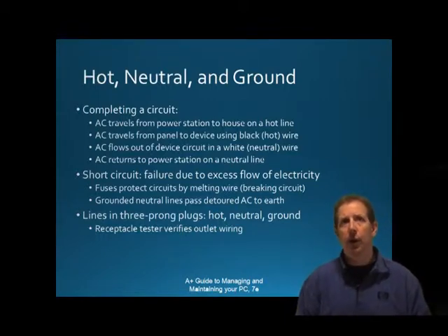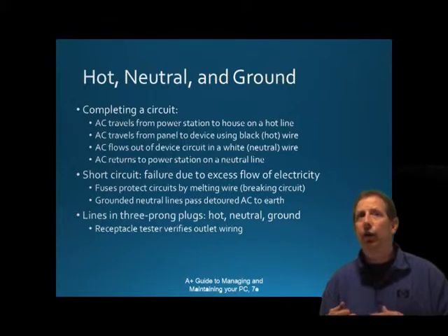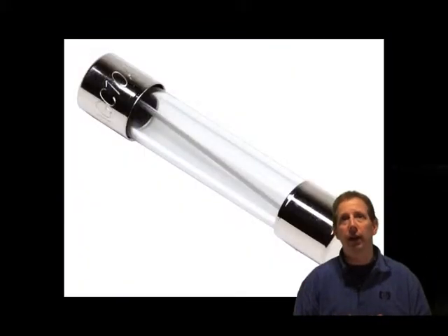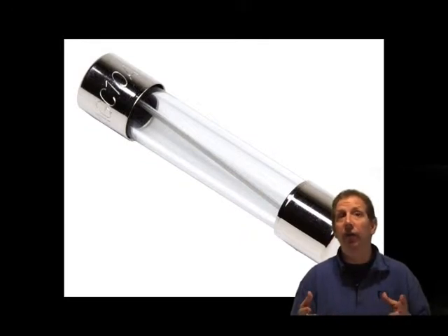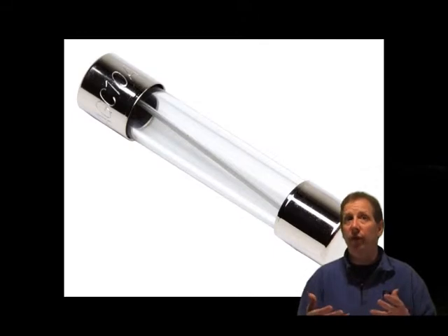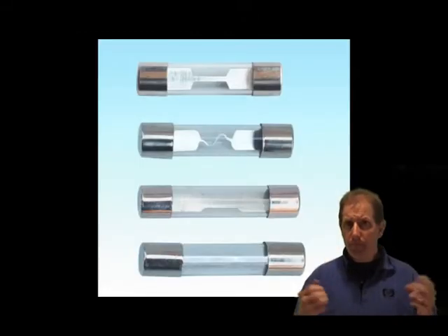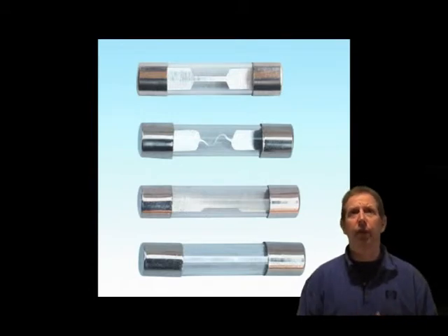A fuse is a component included in a circuit and designed to prevent too much current from flowing through the circuit. It is commonly a wire inside a protective case which is rated in amps. If too much current begins to flow, the wire gets hot and melts, breaking the circuit, as an open switch would, and stopping the current flow.